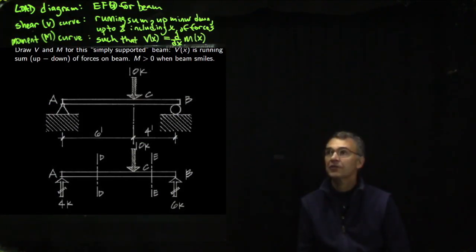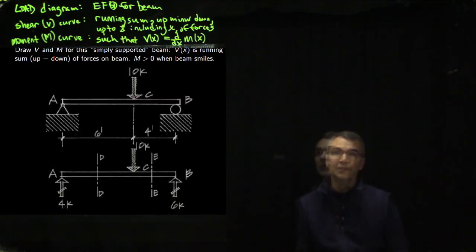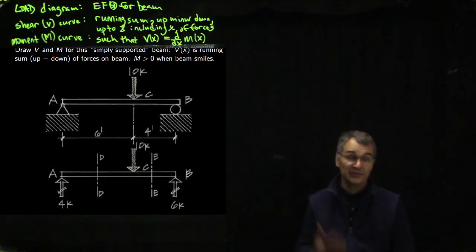So here is a simply supported beam. That means it has one support on each end, and by convention one of them is a roller support, the other one is a hinge support. Let's try drawing the load diagram, the shear diagram, and the moment diagram. Here we go. This beam is labeled with the loads in thousands of pounds. The K means kips, those are kilopounds. Richard Farley laughs when I say kilopounds, but the K is for 1,000, and it's 1,000 pounds.